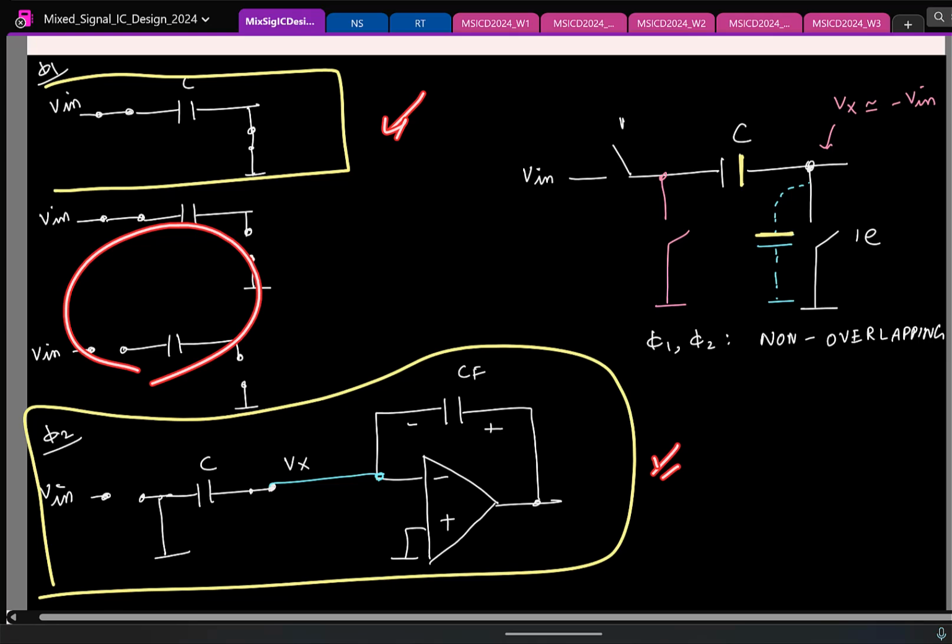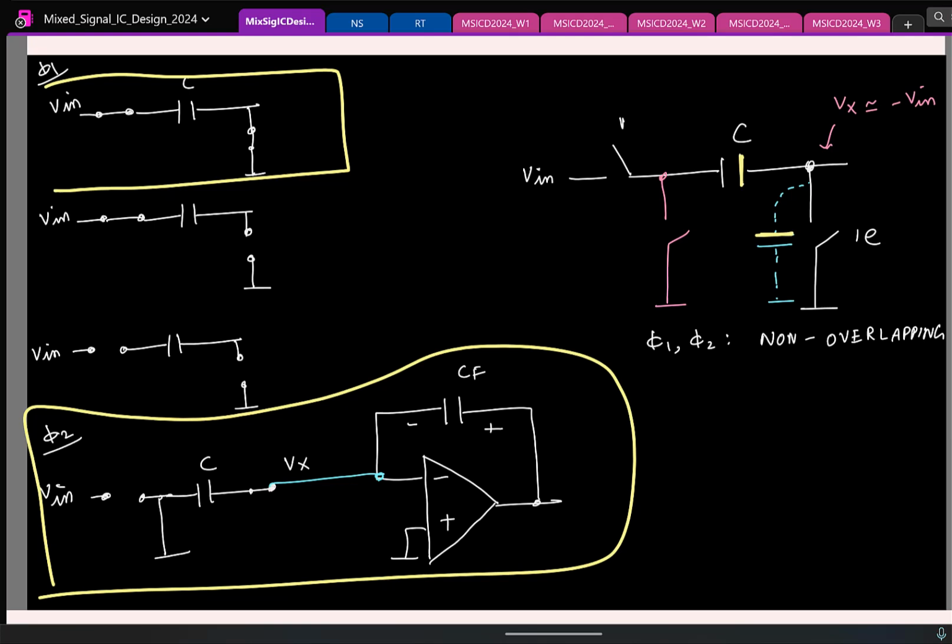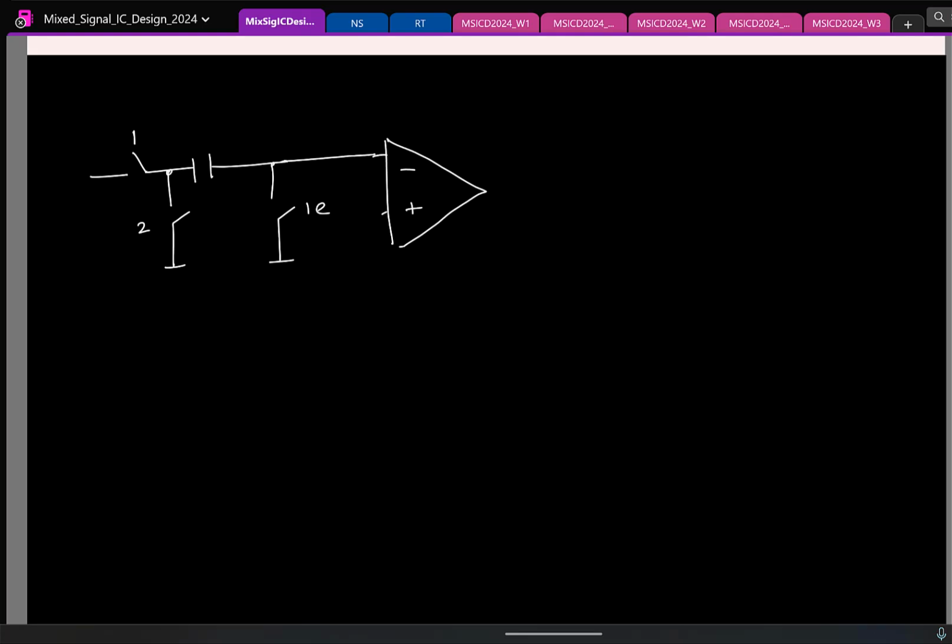Okay. Just to reiterate, the use of the op amp is to not lose the information. Correct. Basically someone has to provide a current, use the op amp to provide a current, that's all. Cool. So now we can draw the complete circuit in both phases. So we have the same thing, the input is sampled in clock phase phi 1, this is the early version, and then in phi 2 you do this, and then you have the capacitor here,